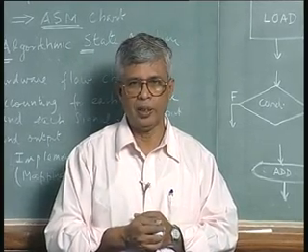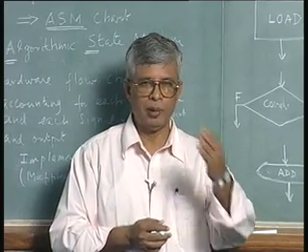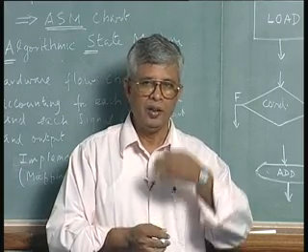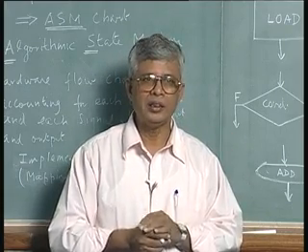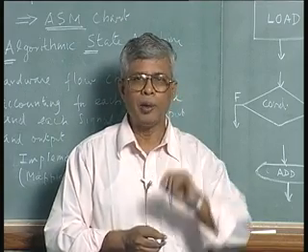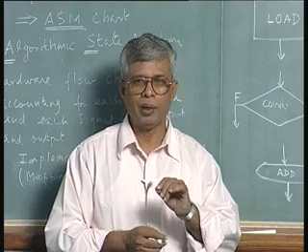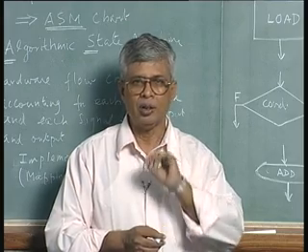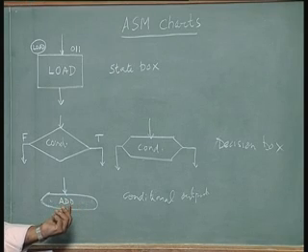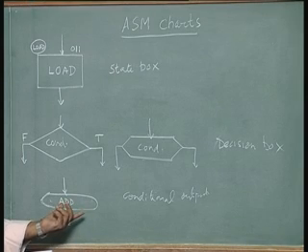When you do a multiplication of two numbers, there is a multiplicand and a multiplier. For each multiplier bit, we add the multiplicand and shift if the multiplier bit is 1. Without adding the multiplicand, we shift if the multiplier bit is a 0. So that is a condition based on the multiplier bit being 1, when we want to add, otherwise 0.